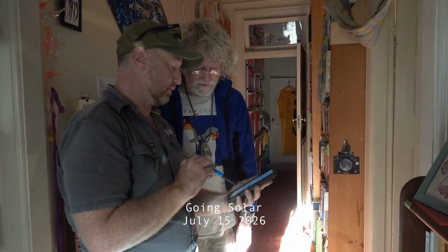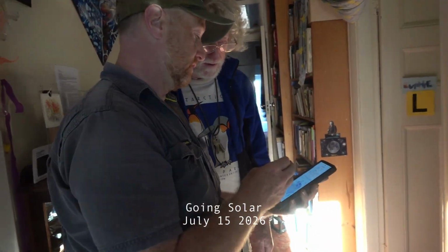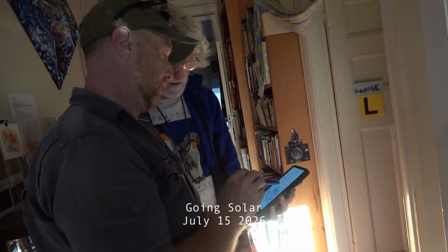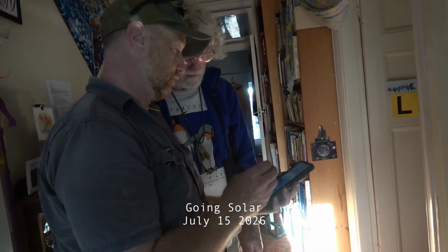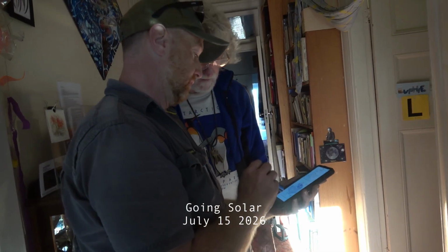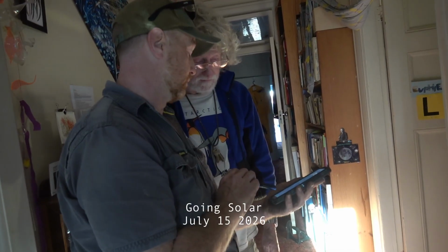This graph here is pretty much real time. So if you turn on the kettle, turn on whatever, you'll see this flow chart change. At the moment you're doing 1.4 kilowatts on your roof. You're using 0.8 in your home, and you can see the remainder is charging the battery. The battery's at 40% at the moment. It comes with a charge on it.